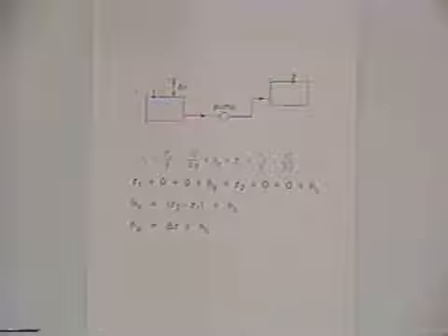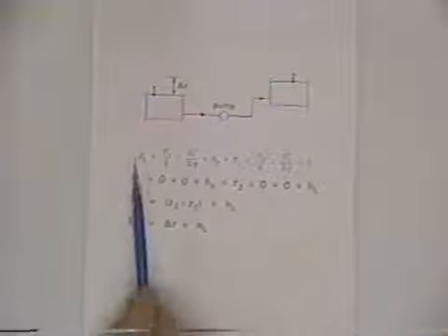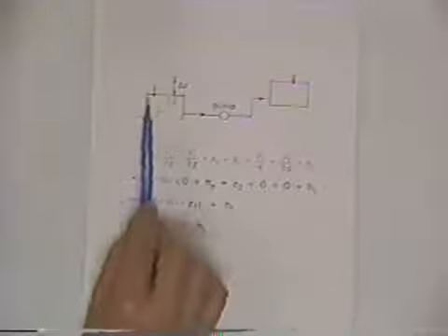And so what we want to do now is take this additional information that characterizes a pump and add it to what we've done already. Let's review what we've done already. We've said that if you're pumping water from one location to another, we can write the energy equation between point 1 and point 2. We substitute in the terms as we've done already. The Z we draw through the water surface and the downstream side of the pump. The pressure head 0, we're back to using gauge pressure again. The velocity head 0. The head provided by the pump.